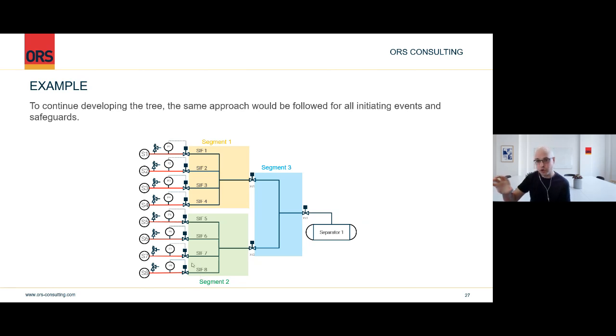So that's why this is more complicated, right? Because as you rightly put it there, Saman, we are used to thinking about one SIF protecting one scenario. That's the way we are trained to see this. And that's why our first instinct is to go through LOPA, right? Or something like that, and say one SIF, one scenario. But for this analysis, you have a different problem where you have several SIFs, one scenario. And then I would consider overpressure not for each SIF, but in the system.